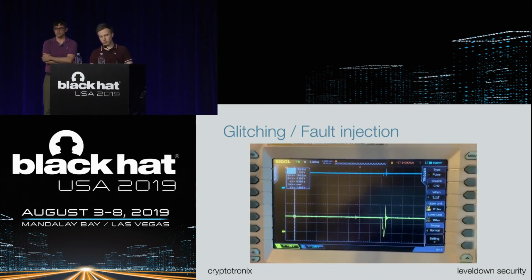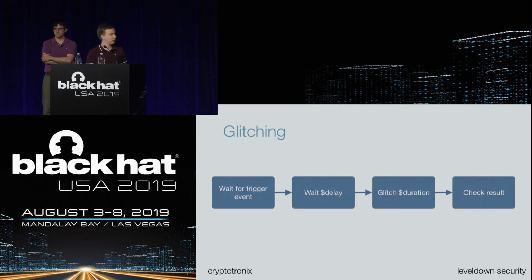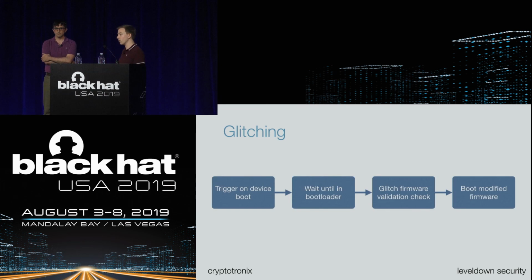Just to summarize, the basic idea behind glitching is you wait for a trigger event, you wait for a certain delay, and then you run your glitch, and then you hope to do something interesting. For example, if you do this on a device, you might trigger on device boot, you wait until you're right in the bootloader, you glitch during the firmware validation check, and you might be able to boot a modified firmware.